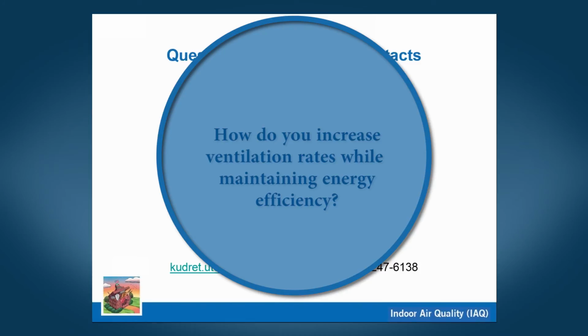Kudrat, I think there's two basic phases to answering that question. One is we have marvelous, reliable controllers today that can base ventilation rates on carbon dioxide, our exhaled breath. One can purchase an accurate carbon dioxide monitor for as little as $128 today, and it will actually work, where 10 years ago you had to calibrate it once a day to get it to work.